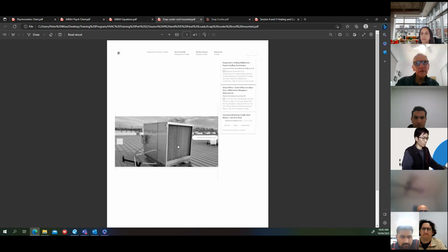So in factories, they quite often use it for cooling the factory space, because all you have is a set of filter pads, a fan, and a pump. And these filter pads here are kept wet. There's a fan in behind there. And there's a filter pad on the other side. So the air's coming in from two directions, goes through the fan and gets blown down through ductwork. In this case, it's going through the roof. That's all there is to it.